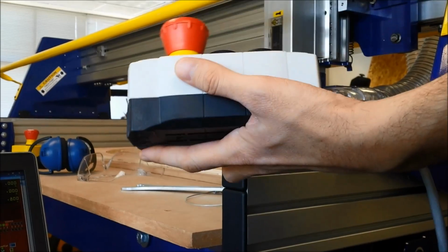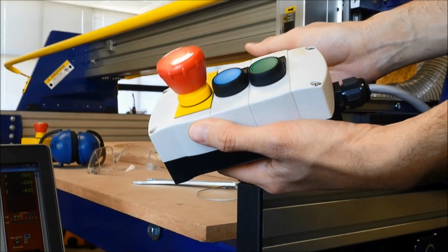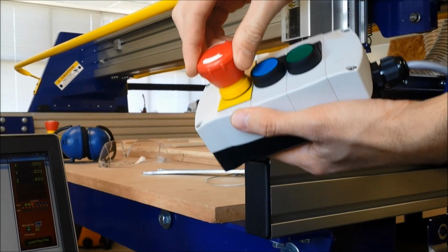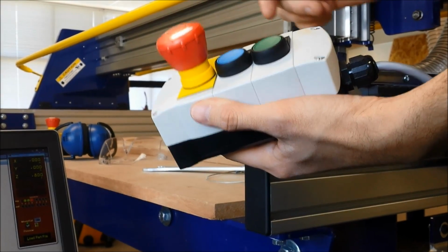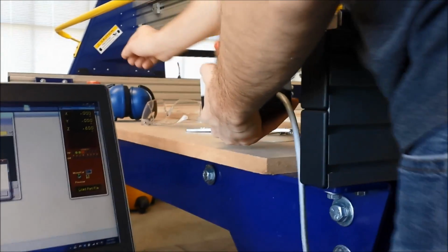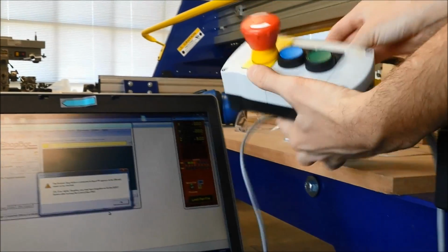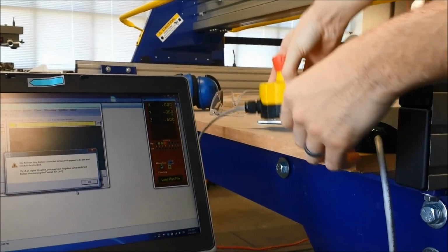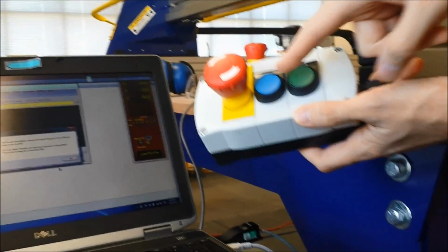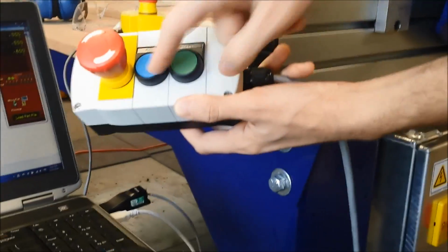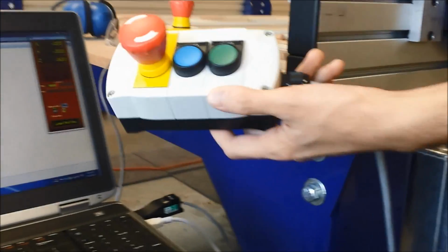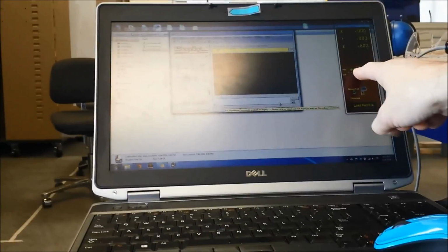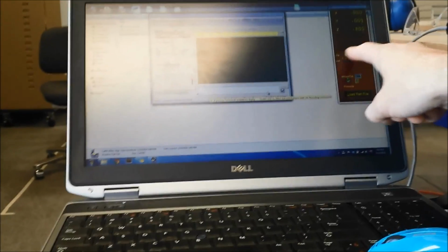That means at some point somebody hit the e-stop. So what you do is you push down and spin it in the arrow direction, and it releases. And we can do that with both of them to make sure that they're good. And then click the reset button. Once we do that, we can click OK, and our stop should be a green light surrounded by a red light.